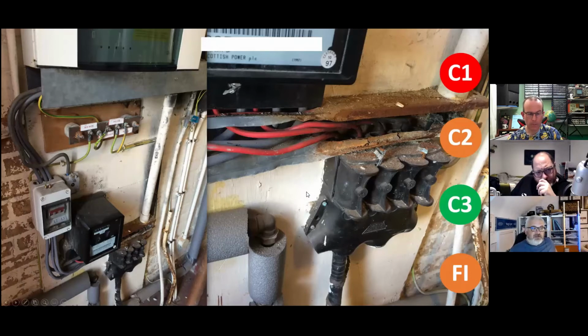And yes, the trunking lid was missing. So no mechanical protection as well. So yeah, C2, I think everybody's pretty right. C1 if there was a small child or something present, not that it would be on a three-phase cutout. Who knows, people with small hands. Trunking fill ratio not right. Yes, it's too packed. 2x2 on a three-phase is never a good idea, really, is it? Okay, let's move on.